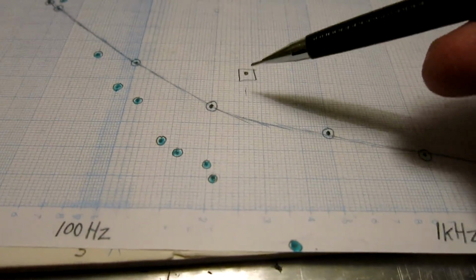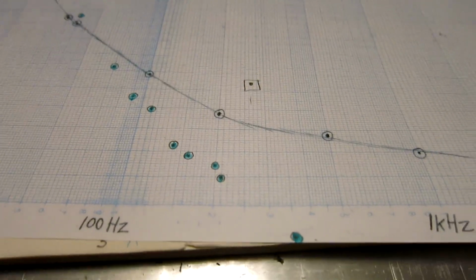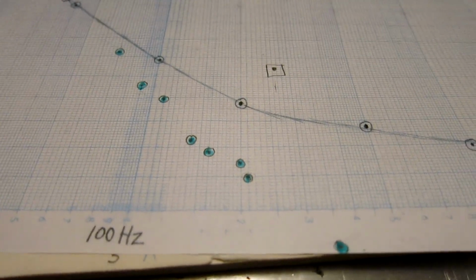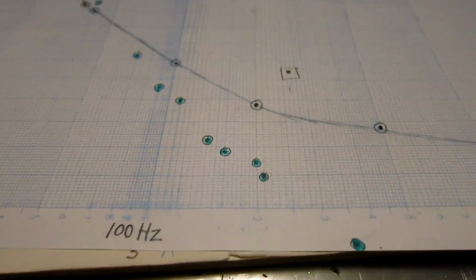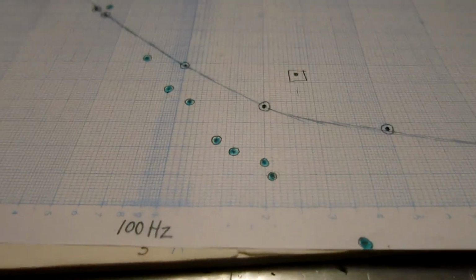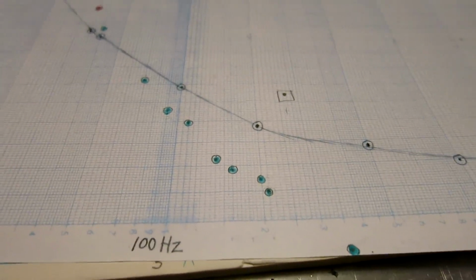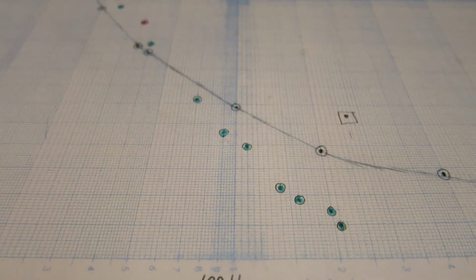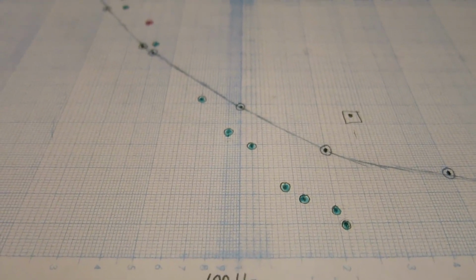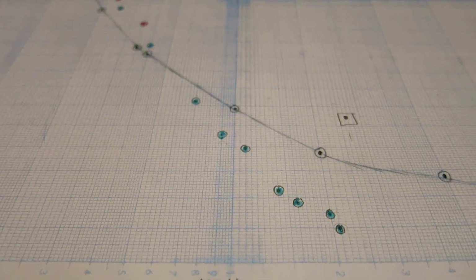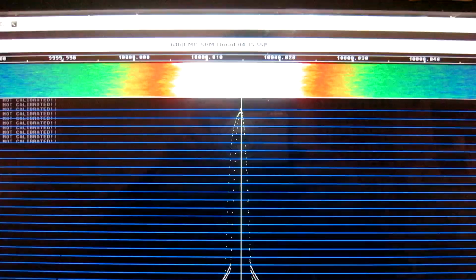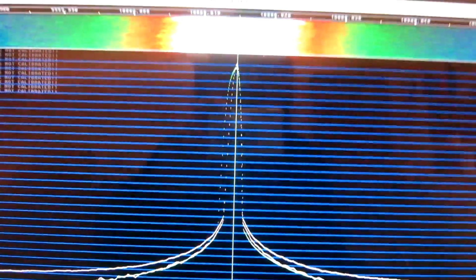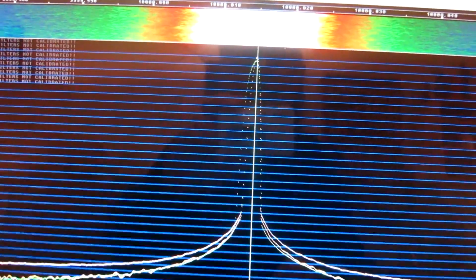So allowing amplifier gain compression to set the level of oscillations in this kind of oscillator is a bad idea. And I don't need to evaluate more points from that image, because I can see that the values are really bad. I just checked the delta 44 also. There has been some frequency drift, but not that bad.